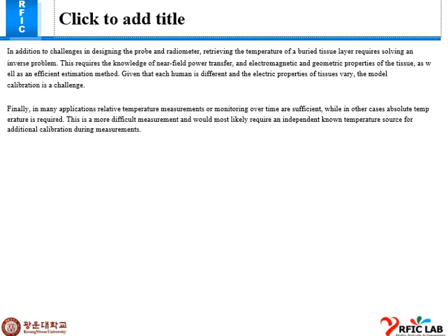And there are other challenges also. In many applications, relative temperature measurement or monitoring over time is sufficient, while in other cases absolute temperature is required, which is more difficult to measure and would more likely require an independent known temperature source for additional calibration during the measurement.